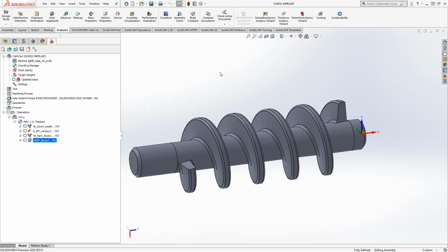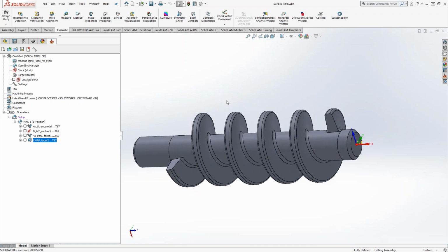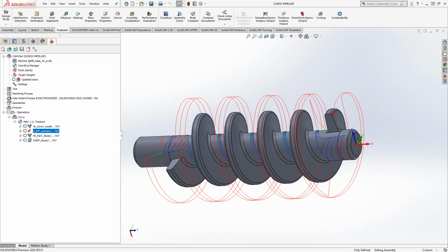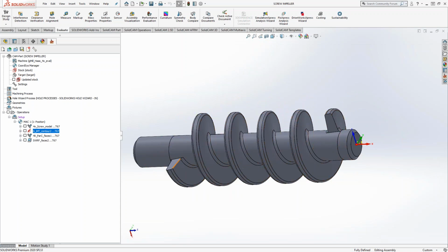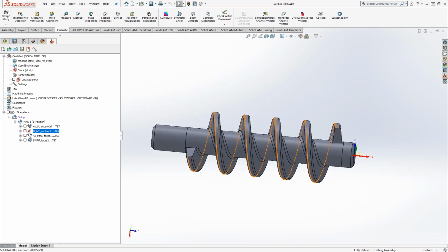It's a really good suggestion because if you have 3D iMachining, regardless of the fact that this is a 4th axis part, you can probably get some better cycle time without having to index this thing. You can just lock it in place, do 3D iMachining, do indexing 2 times or 3 times or even 4 times, depending on the reach of your tool, and you can get this thing done. 4 times probably is not going to be necessary here because I think I have enough reach on the tool. What do you think, Kevin?